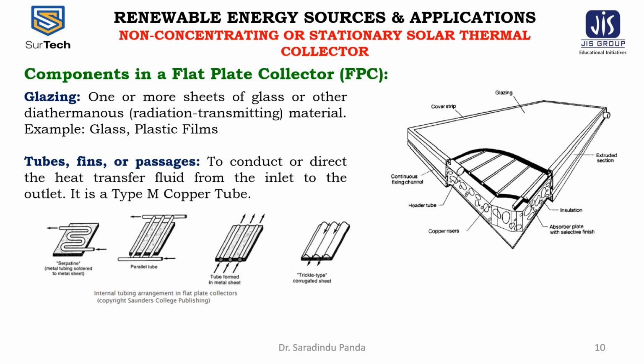Plastic films and sheets also possess high shortwave transmittance, but because the most usable varieties also have transmission bands in the middle of the thermal radiation spectrum, they may have long wave transmittance as high as 0.40. Plastics are also generally limited in the temperatures they can sustain without deteriorating or undergoing dimensional changes. Only a few types of plastic can withstand the sun's ultraviolet radiation for long periods. However, they are not broken by hail or stones, and in the form of thin films they are completely flexible and have low mass.